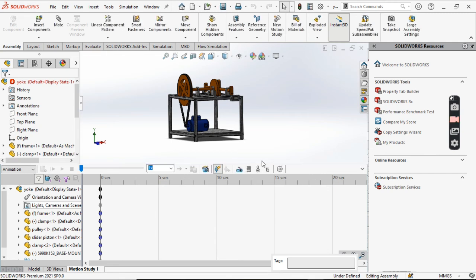The next one you move to, we don't need a contact. Why don't we need the gravity? Because we are not doing anything that has to do with gravity. Nothing is falling. Are you getting it? So we just want to have a mechanism, a principle, of how the power is being transmitted from the prime mover to the shaft. So the gravity might be neglected for a while because it doesn't have a real effect on it. And the contacts, we won't be using much of them, because mostly they are made for follow-up stuff, but we are not going to be using it.